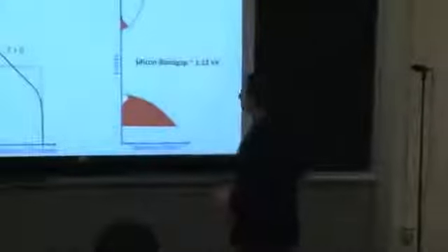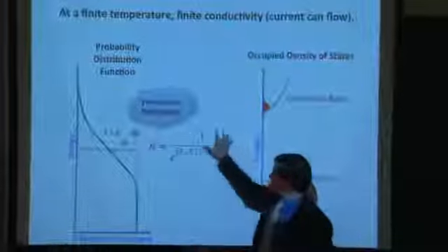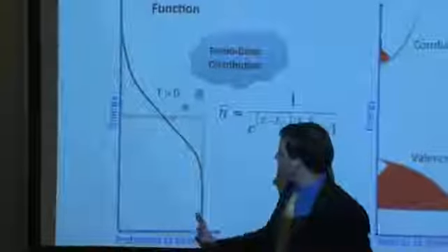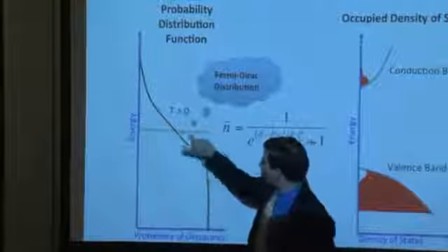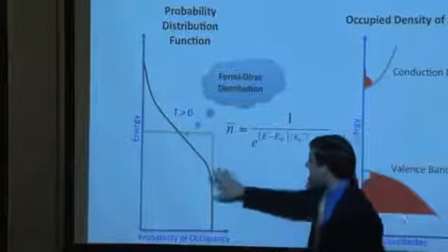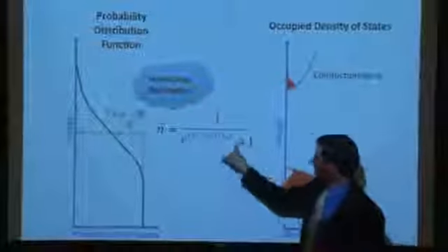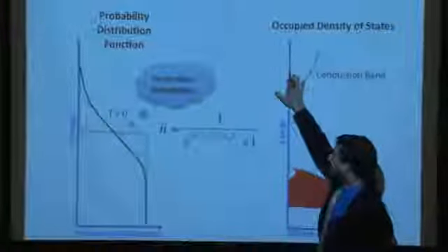So what we're going to do, as Joe sets this up, is I'll verbally describe what's going to happen here. Let me go back to the Fermi-Dirac distribution function. As we increase temperature, this will look more and more flat. It won't actually go flat, but it'll become more and more diagonal as opposed to box-like. What that means is the density of free carriers will increase with temperature, and because of the Arrhenius dependence, we have an exponential increase of the number of free carriers with temperature.